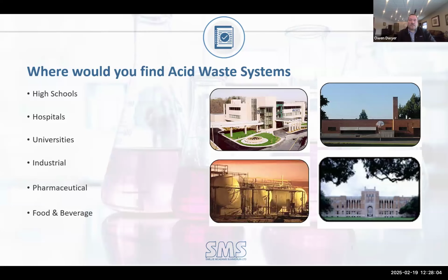Where you're going to find corrosive waste applications: your typical high school, university type of lab, hospital labs for sure, industrial applications if they've got chemical process washdown, pharma is obvious, and surprisingly, a lot of people aren't familiar with the food and beverage requirements for corrosion resistance, and that's again chemical sterilization of vats, things of that nature. So a lot of detergents, a lot of soaps. Sometimes you cannot discharge because of the pH. Discharge limits have to be dealt with, and I'll talk about those here momentarily.